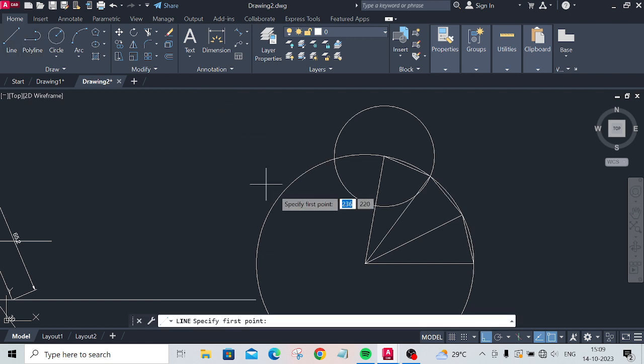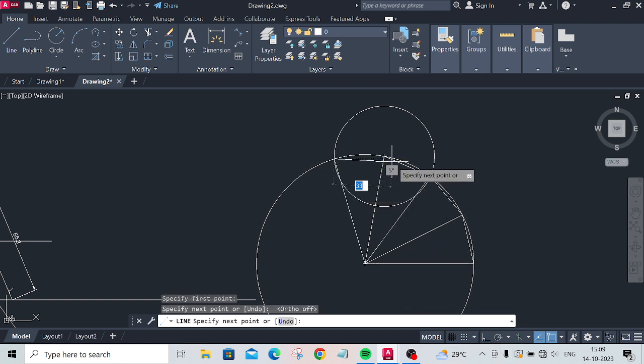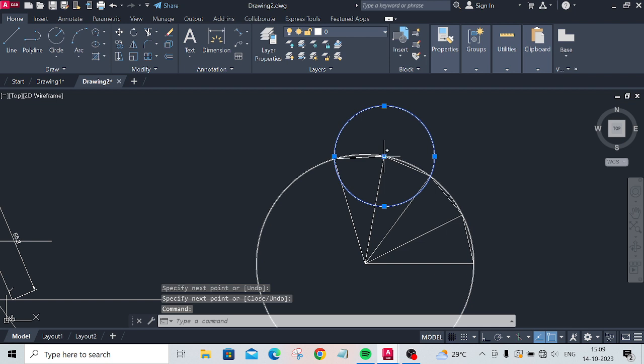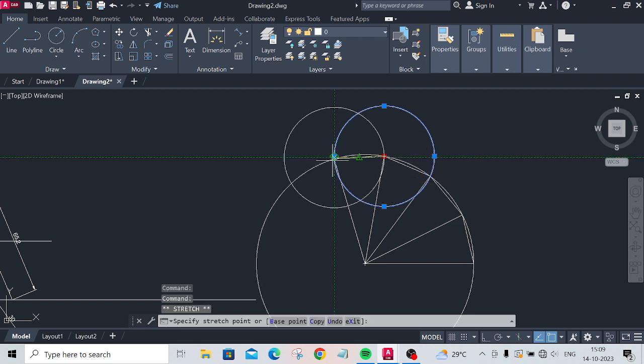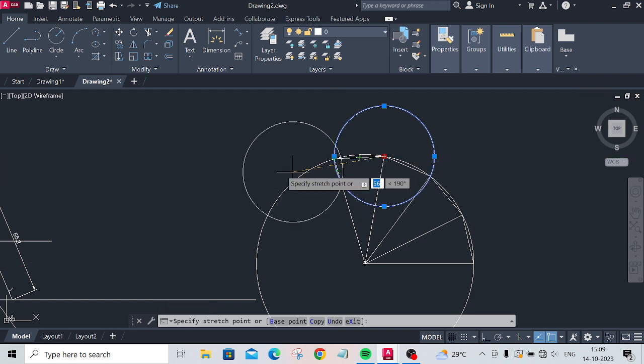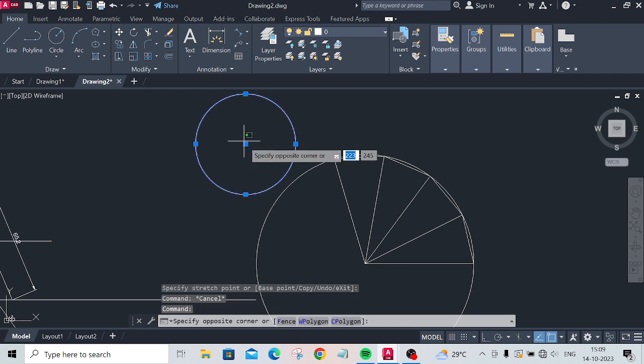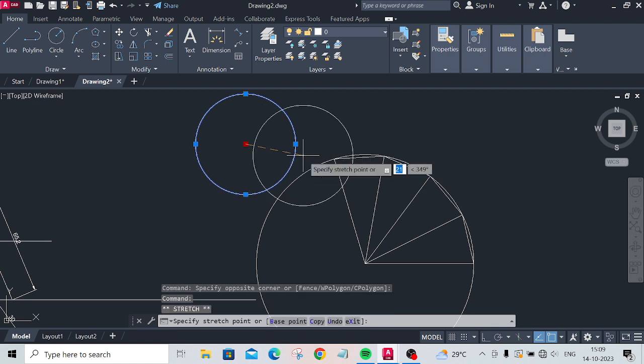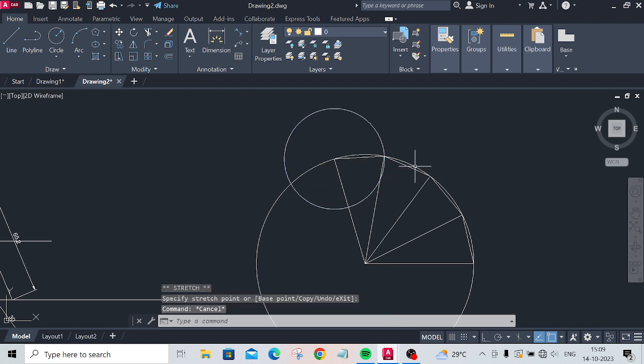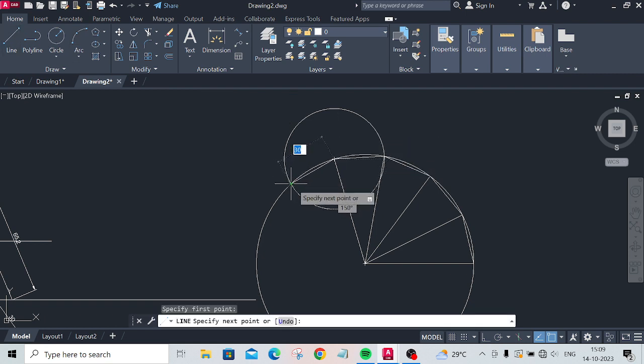Now draw a line. It's ortho mode off. We are drawing an inclined line, so you switch off the ortho mode. Now move it to the final triangle. Zoom onto the exact intersection. Move it away also, and thereafter you can move it. If you are facing any problem, you can pick and drag it to this point. Okay, and then you draw the final triangle.